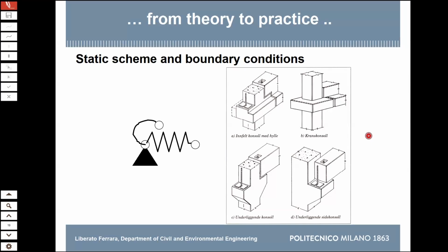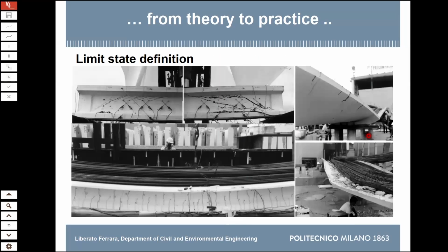But also, depending on whether your connection is simply this or has also some other stiffness, if you go into dynamics, which is important for earthquake, the frequency of the vibration modes can change. You might have a stiffer structure, and a stiffer structure may also mean that the inertia effects are felt stronger. So may not be always.